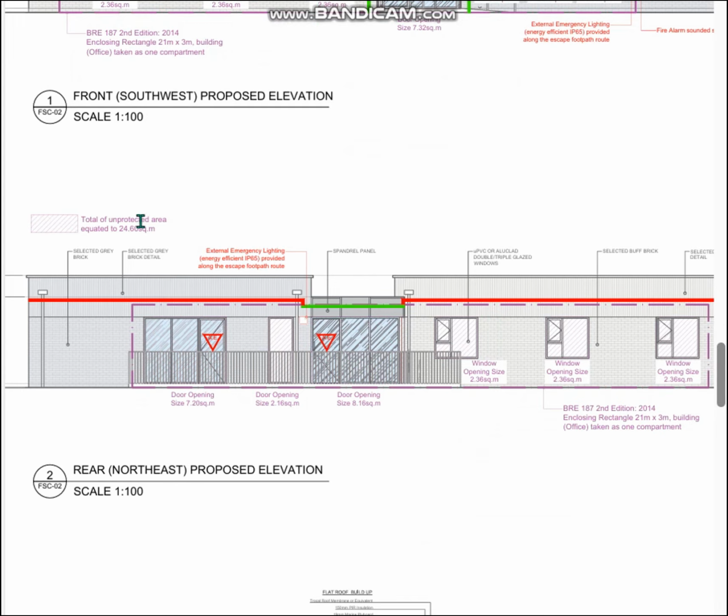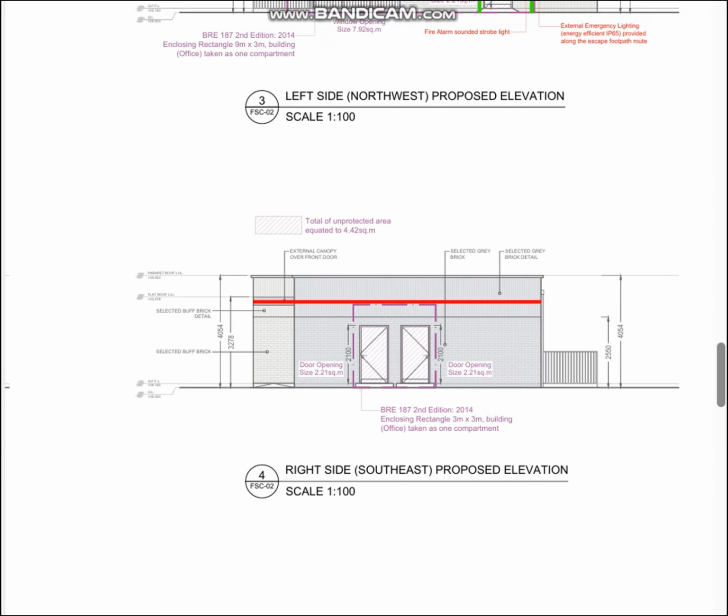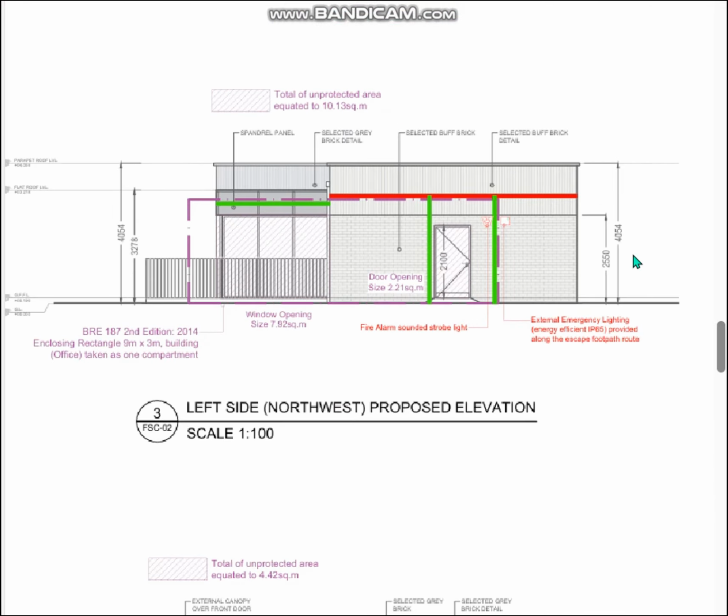First of all, the total unprotected area is calculated. This is usually openings in walls for windows and doors, or some other openings or materials that may not have the necessary fire rating in terms of integrity, insulation, and stability.